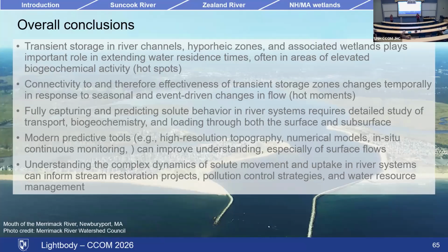If it's coming in the subsurface, or at the bed, you can't see it on the surface usually because it's denser and so it doesn't rise up. So you would need to use a distributed temperature sensor or something else in order to pick up that cold water input. We'll look for the brook trout that seems to sit there. You could just look for the brookies, exactly.